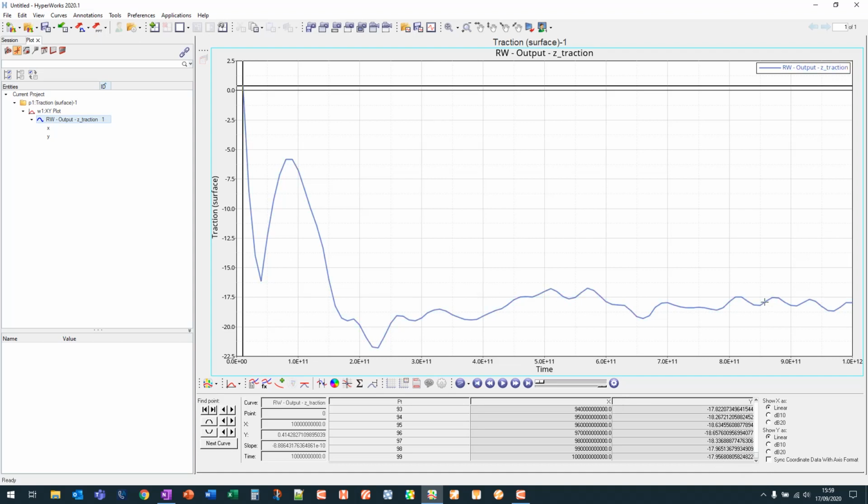What you can see here is that there is a little oscillation on the rear wing, and based on looking at the convergence criteria and the solution ratio of the simulation, you can see that there's quite a lot of turbulence coming off the rear of the car, and this is a highly transient phenomenon, and trying to model that in a steady state fashion can be particularly difficult, hence why you see changes in the values here. So one way to resolve that is to run a transient simulation, which will run a little bit longer, but you'll see that the surface outputs will either smoothen out or oscillate, and you can take a time averaged value for the forces, the pressures, whatever they may be.